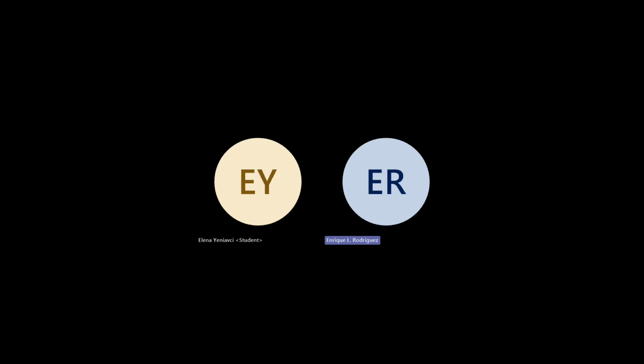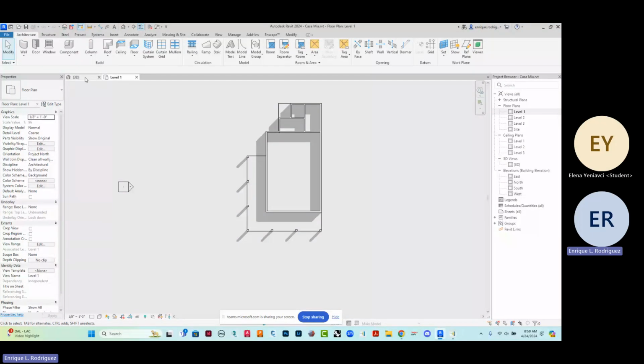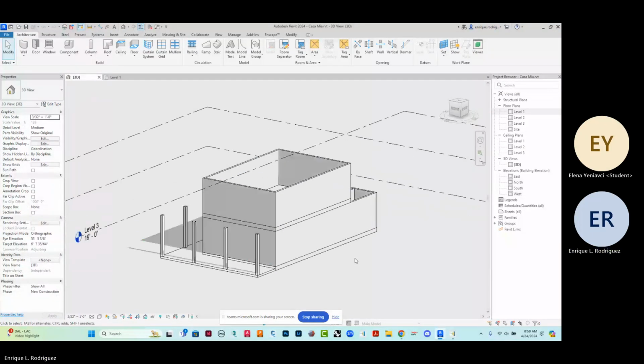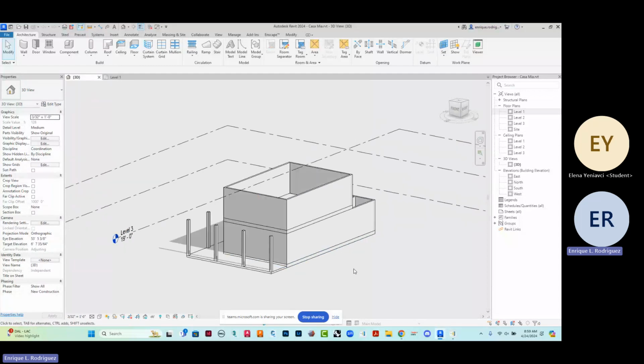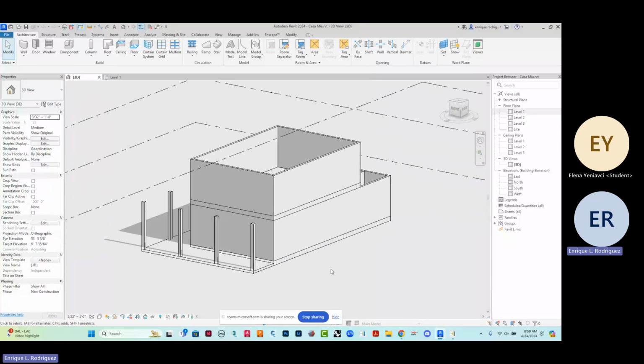All right, this is the second video for the Mallory, and we're going to deal with roofs for the Mallory. Now, one thing that I discovered through mistakes was that there is a huge difference when you tag and select roofs for creation, whether you select walls or you select lines, etc. The way that the overhangs and or offsets work are totally different.